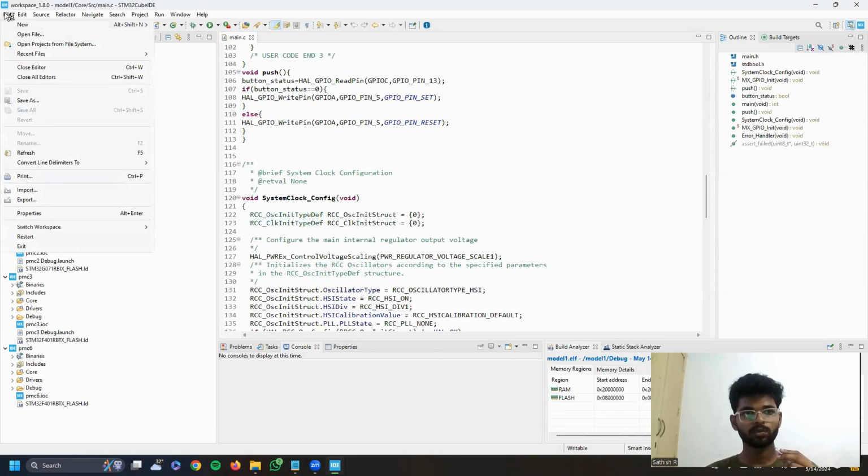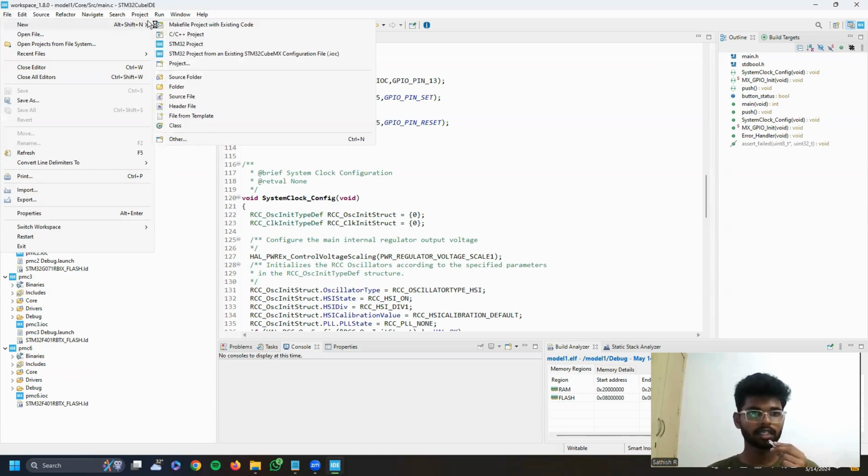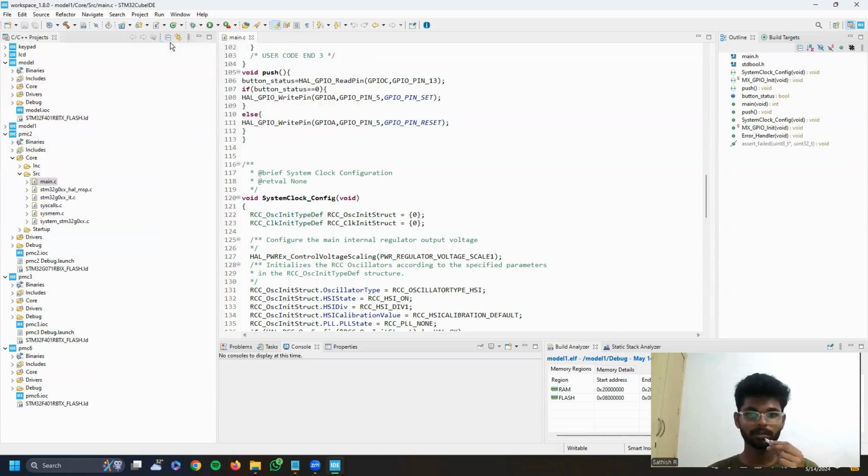I am going to create a new project. For that, click on file, click on new and click on STM32 project.